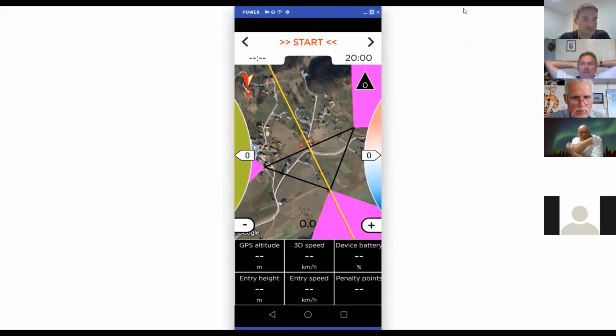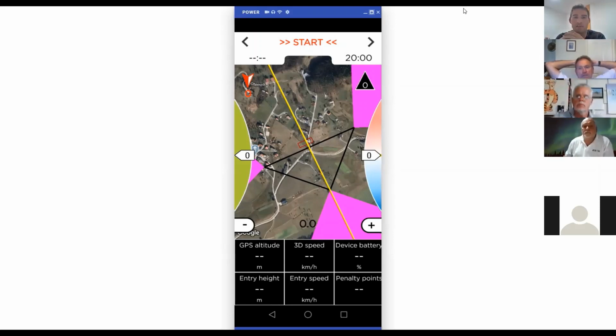Okay, I have 2 questions. Aro asked me, where are the wind speed and direction coming from? Okay, the speed of the wind comes from calculation. If you have the Raven and an airspeed probe connected to it, it will calculate the difference between the airspeed and the ground speed. If not, it will calculate when you start thermaling how much you are drifted away and the difference of the speeds, the maximum and minimum ground speed, when you are thermaling. So this works very accurately with the scale gliders, with light class, depending on your installation of GPS. If GPS reception is bad, the wind will be bad. If the installation is nice, so you can see very nice circles when you thermal, it will be a very nice and accurate demonstration of the wind.